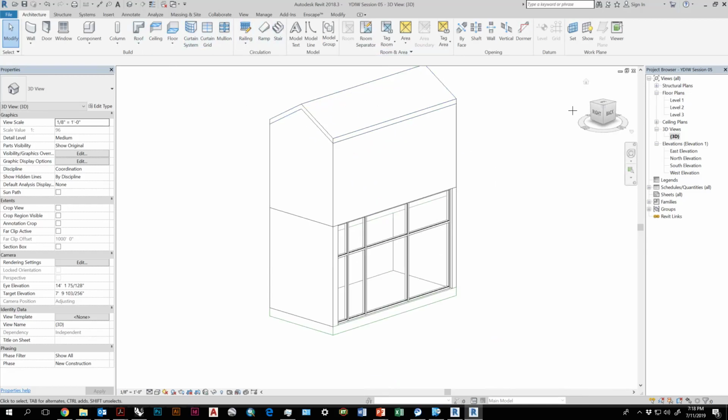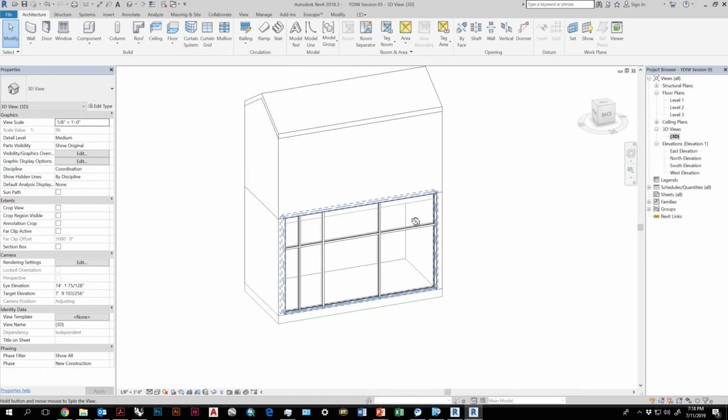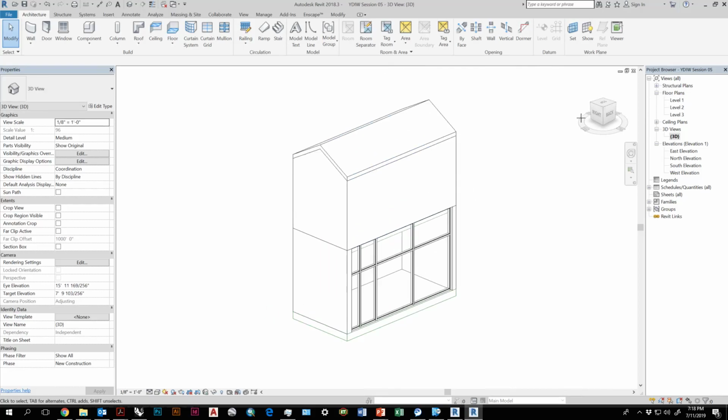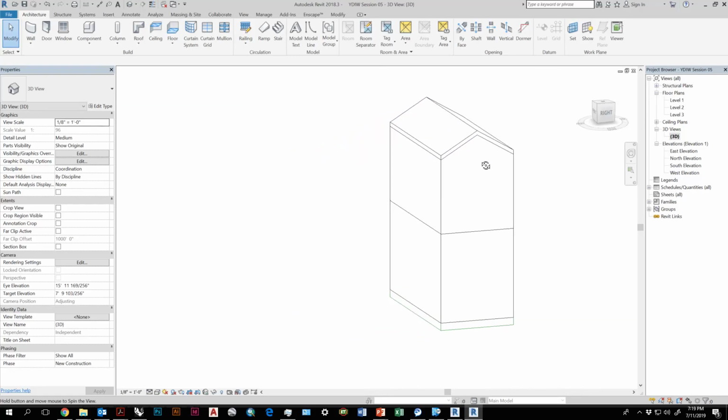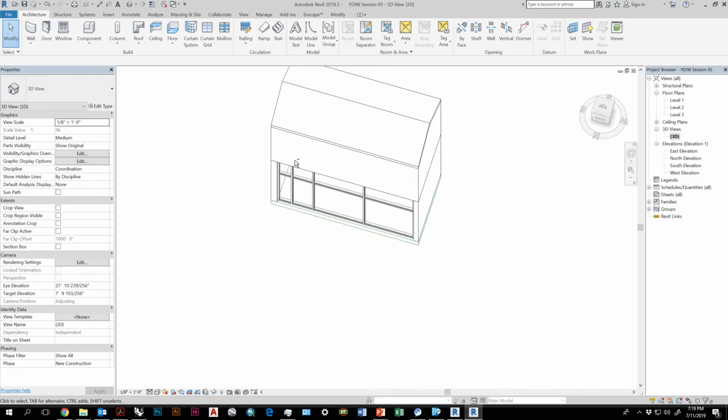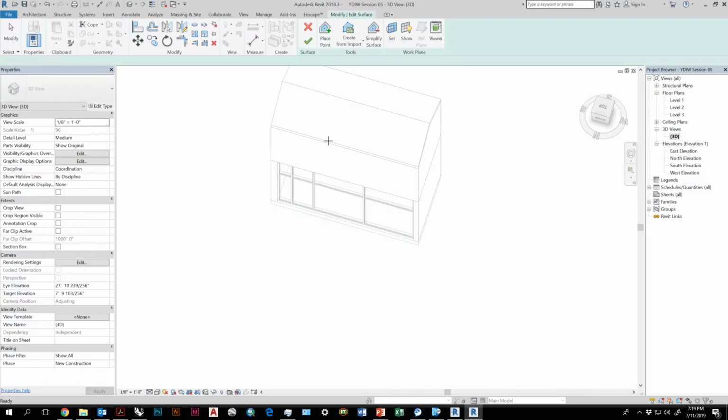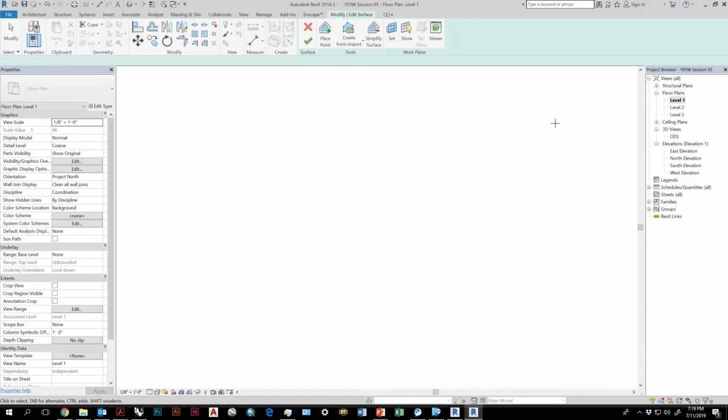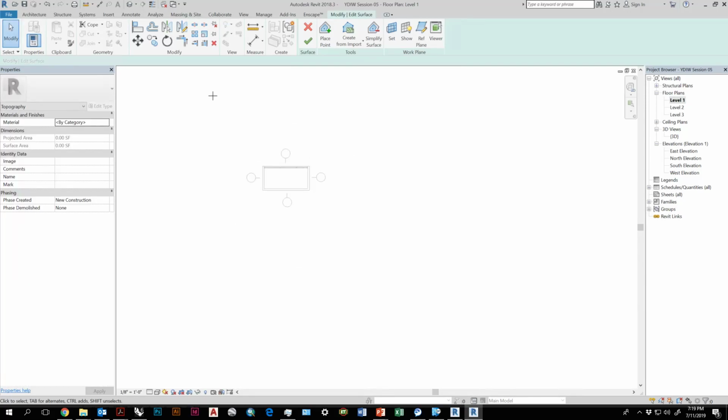So let's say we wanted to create some perspective views. I'm going to go ahead and create a site super fast. Sites are basically the environment that your model exists in. You can either create it by placing points in some strategic locations. So let's say I'll place a point here, here, and here. And now the surface is starting to be made.